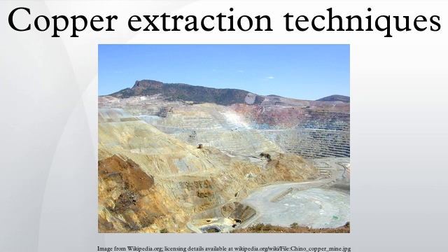As in all mining operations, the ore must usually be beneficiated. To do this, the ore is crushed. Then it must be roasted to convert sulfides to oxides, which are smelted to produce matte. Finally, it undergoes various refining processes, the final one being electrolysis.